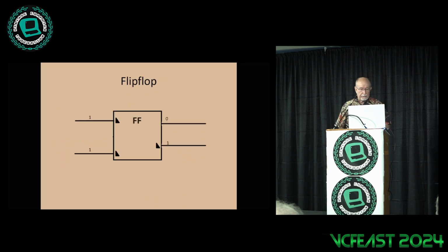So I have a flip-flop. That seems pretty straightforward, right? Only thing slightly different is the flip-flop has inverted set and reset, but it's a lot like an SR flip-flop. So we should understand this, and to a large extent you do. If you send a negative pulse on the set line, the flip-flop changes.